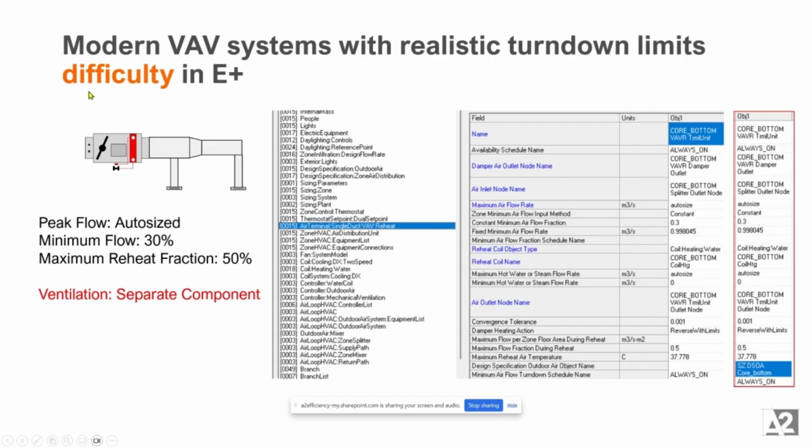And so just to show again where this plays out in different objects in EnergyPlus, I've highlighted here this single duct VAV reheat air terminal device. This is a screenshot from EnergyPlus 25. As versions change, I'm sure there'll be subtleties, but by and large, this object has been around for a long time. We don't really expect it to change anytime soon.